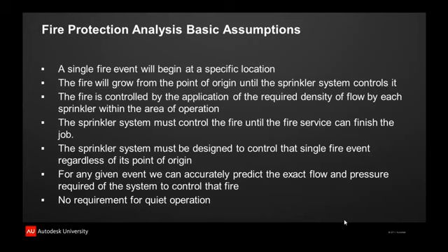Next, the sprinkler system must control the fire until the fire service can finish the job. So it doesn't have to operate all day long every day. It's just when there's a fire, and only until the fire department shows up and actually puts the fire out. This is pretty key, that our design basis or our assumption is that we're trying to control the fire. We're not, generally, trying to put the fire out. Simply control it long enough for the fire department to show up.